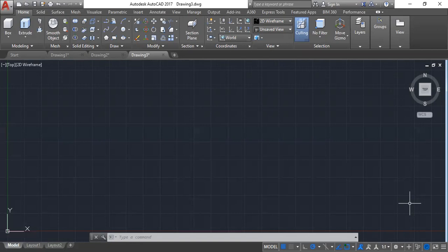To start, I'll first explain extrude. To be able to explain extrude, I need to draw a shape. So what you're going to do here is this. I'll click on the rectangle tool, and then I'll draw a rectangle. I'll then go on and add depth to this rectangle. Now, to be able to add depth to the rectangle, you have to